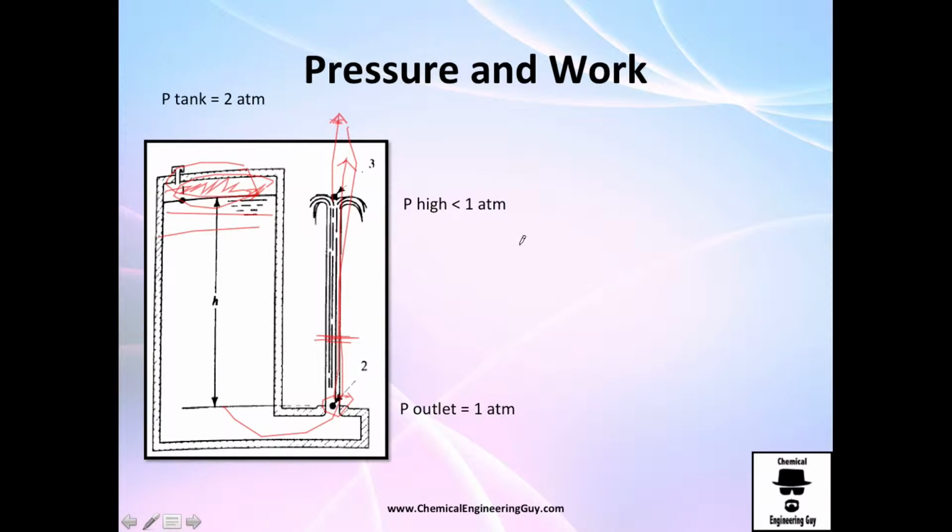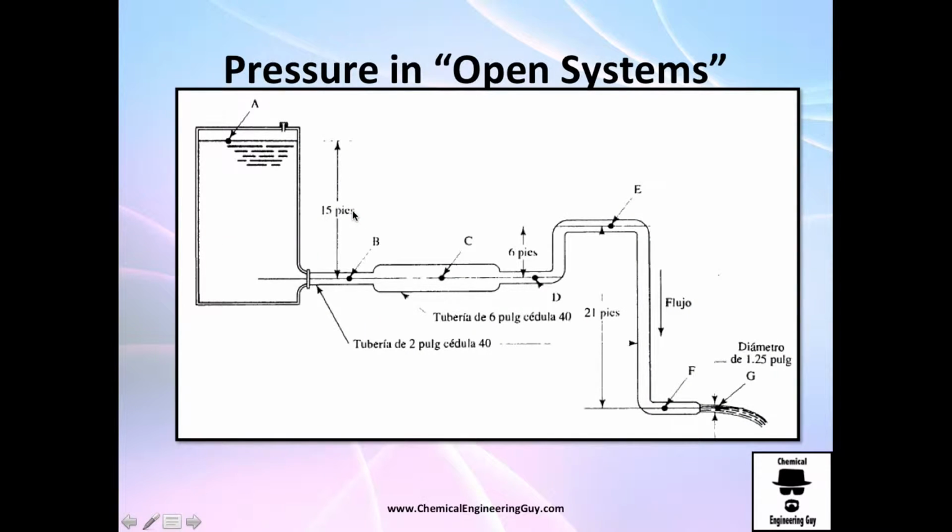So maybe you are getting the idea of how we are transferring pressure to height, or at least how the differential of pressure will give the system a higher or lower level, because we are transferring energy, pressure energy, to potential energy.